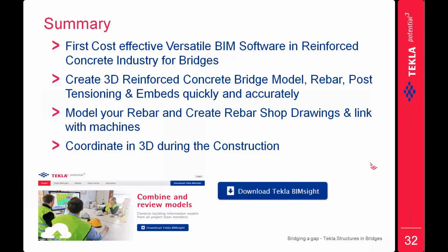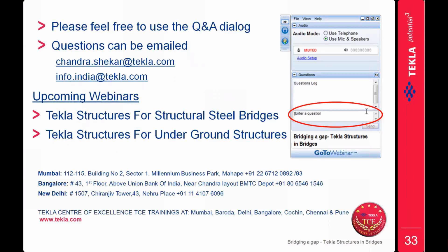And to automate the process, we can even link with the machineries also. So the bar bending information goes to the machine, and according to the shape code, it cuts and bends the rebar as per the reinforcement arrangement we did in the bridge model. And we can communicate with the site people by using the free tool from Tekla, that is Tekla BIMsight, during the construction.